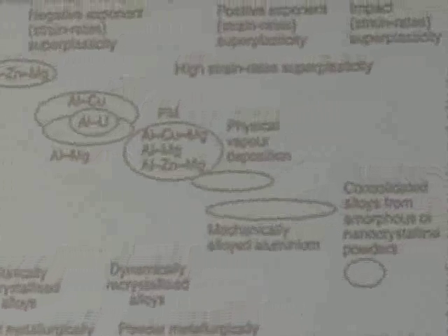can vary. They've got orders of magnitude here, but basically aluminum, zinc, magnesium alloy, some of your 7000 series aluminum alloys used in aerospace, they may have grain sizes on the order of 20 microns. As you get finer and finer grain, creep becomes easier and easier. In fact, we try to get rid of grains when we want to get the best high temperature creep properties. We actually go to single crystals to completely get rid of grain boundaries.